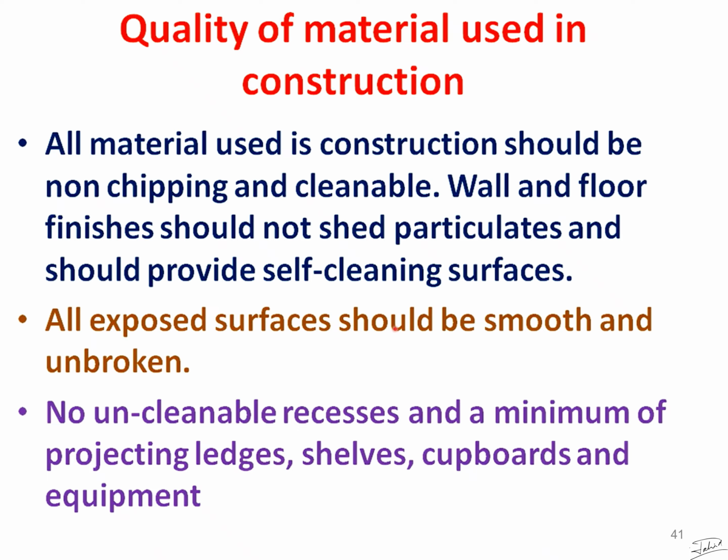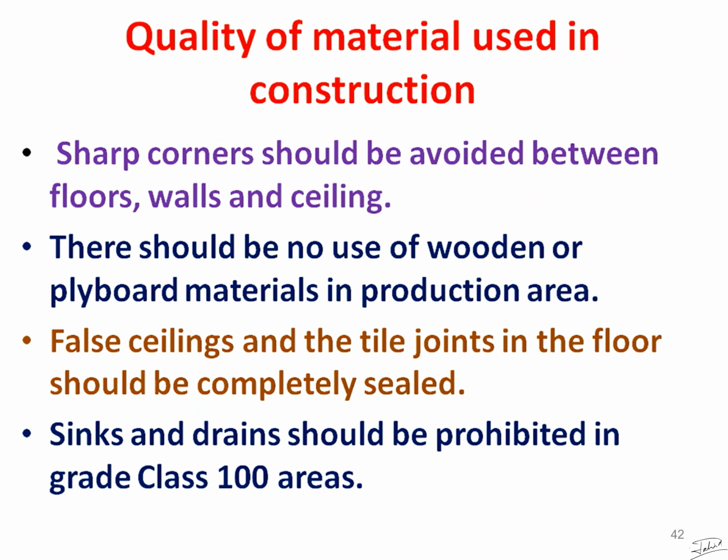All exposed surfaces should be smooth and unbroken, otherwise this can generate dust. Okay, so no uncleanable recesses and a minimum of projecting ledges, shelves, cupboards and equipment. Sharp corners should be avoided between floor, walls and ceiling because bacteria can accumulate there. There should be no use of wooden or plywood material in the production area because this can generate dust. Okay, false ceiling and tile joints in the floor should be completely sealed, and sinks and drains should be prohibited in grade class 100 areas.